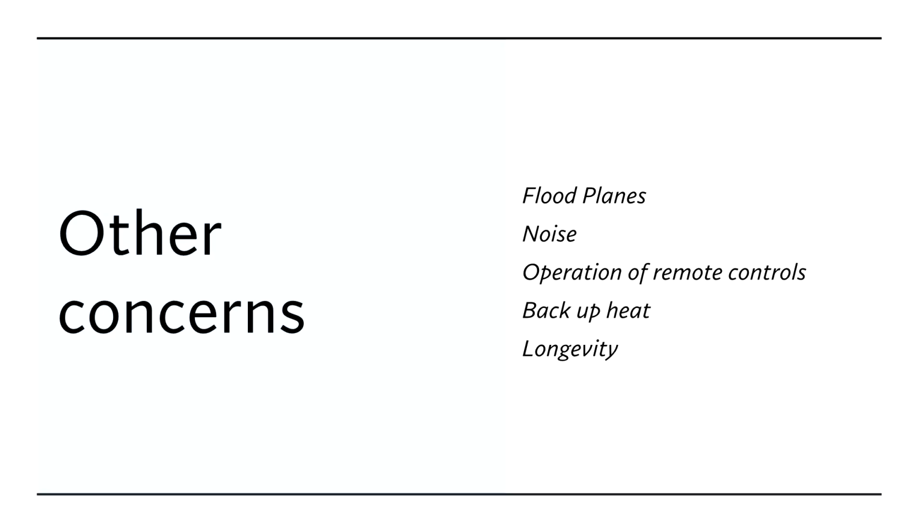They tend to, through the inverter unit and the computer systems that are on board with this, measure temperatures all over the place on the indoor unit. On the outdoor unit, it has multiple temperature sensors, and it's making adjustments to things based on what it's been programmed to do. Okay, so if a space is cold, it will ramp up the compressor, ramp up the outdoor fan, and send a signal to the inverter or the indoor unit that we're actually going to put some more heat into you. All right, so that's kind of that stuff.